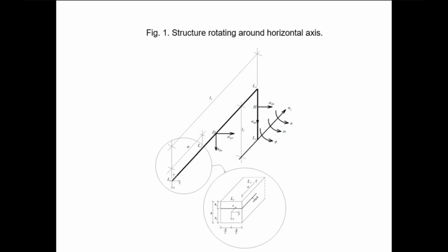Since the rotation is non-uniform, both normal and tangential accelerations are induced. The intensities of the distributed inertial loads in the structure due to the normal and tangential accelerations are derived. There is a longitudinal crack in the horizontal member of the structure. The strain energy release rate in the structure under the distributed inertial loads is determined. The influence of the normal and tangential acceleration on the strain energy release rate is investigated. The effects of various parameters of the model are studied.